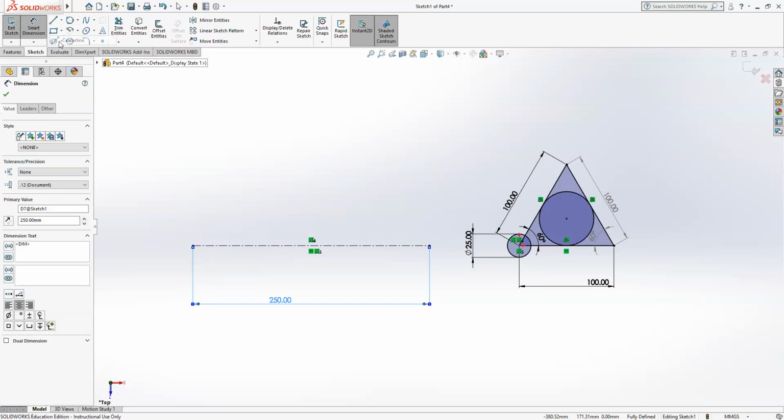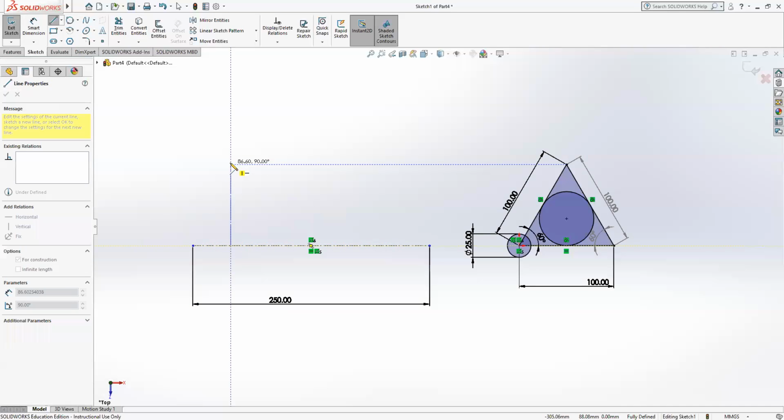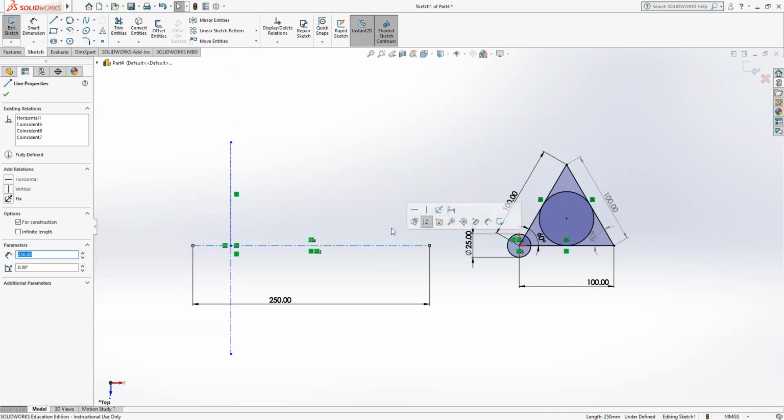And then we'll go over here, we'll do two more center lines, all right? So we'll do a center line here. And you remember how I said if you pull up and you're perpendicular, you get that yellow cursor? Well, when you're doing center lines, you also get this grid that pops up where it shows you that you're actually perpendicular along the lines. So we'll draw one up and we'll draw one down a little bit. Say escape. And then we'll do the same thing over here.